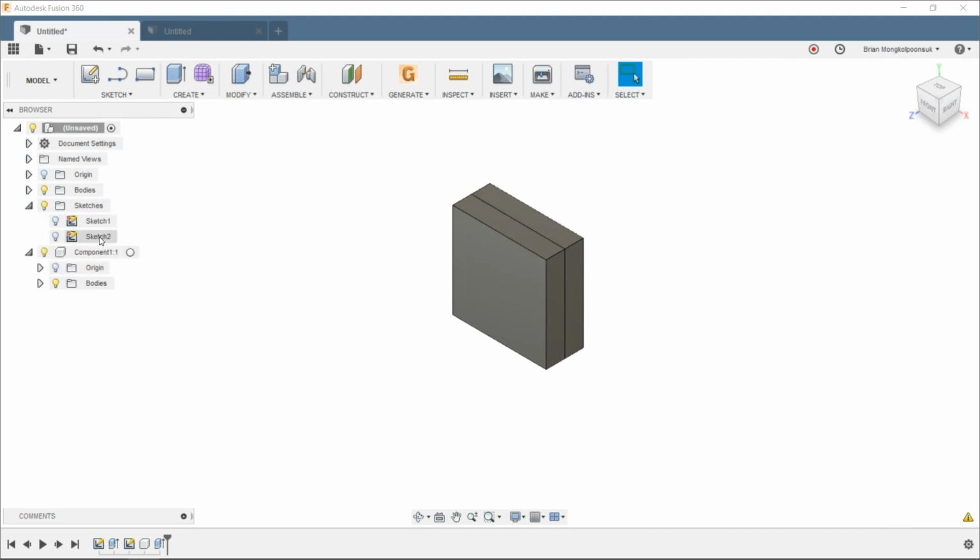So now your sketch number 2 is up here in the sketches folder in the assembly workspace, whereas the component that you just created for number 2 is down below here without that sketch. And you can't just drag and drop it into here, unfortunately. I've tried that many times before to try to fix the problem, but it's essentially there forever, and it's separated.